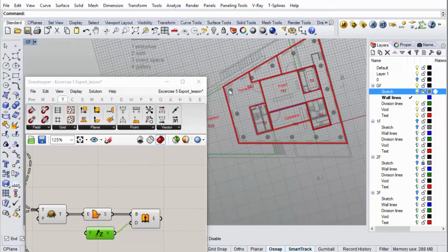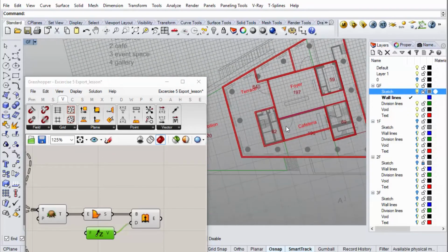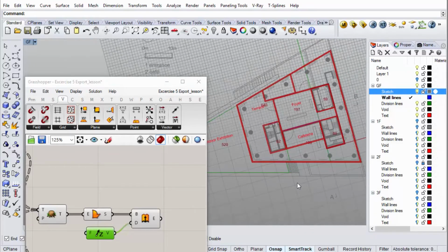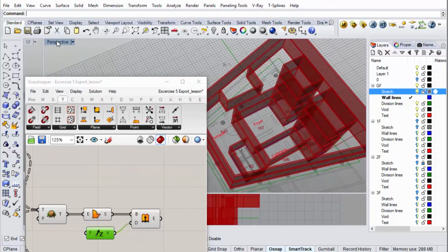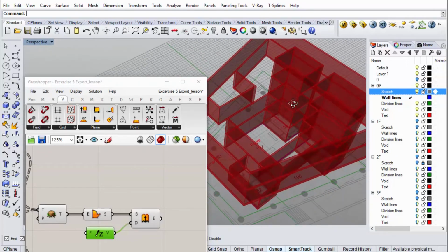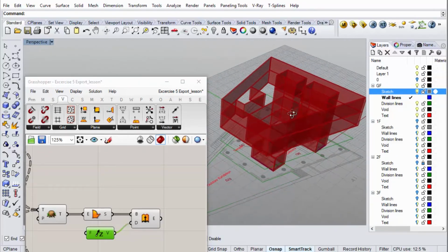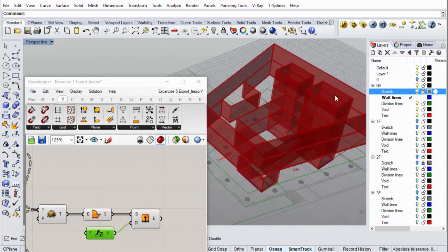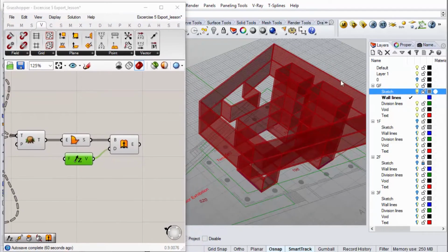Then you can start to work on wall widths and so on, adding detail. But once the sketch is solid, once the areas check out, once you know you're meeting the program, then it all becomes much easier. So CAD becomes an exercise of adding detail and not playing around and making it work. So the playing around bit you can do very, very quickly with the sketch tool, and then work detail into CAD.